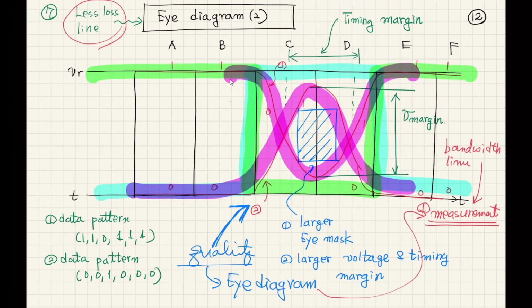Your oscilloscope and your probe are not a perfect measurement tool. It has certain limitations because of the capacitive load and transmission line impedance. And also you have to use probe structures and cables, and then you're gonna also have high frequency loss as well. So measurement is very, very limited.